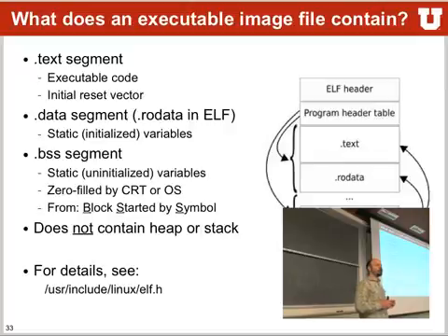Who knows? If you have a variable that you have not initialized and you start using it without assigning anything to it? Yes? It contains whatever's in that location, right? Yes. So it's not guaranteed that an uninitialized variable is actually 0. Now, many systems try to do it. Because these variables all sit in the BSS, what oftentimes happens is that your OS goes into that section in the very beginning of the startup of your application and just writes zeros all over the place, making sure that everything is 0, but it's not guaranteed that this really happens.